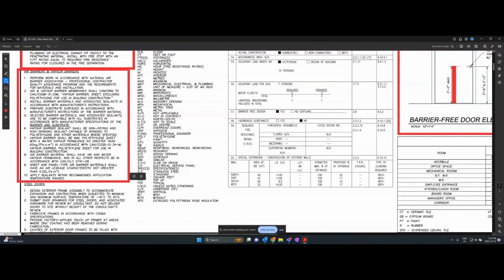other materials where specified. So basically what it's saying is that it's always going to be a little bit liquid in order to have the vapor barrier sealant not get hard and crack. So the caulking doesn't get hard and crack and fall out of the joints or make the air come through. So you always have to have that with a little bit of movement and not drying.